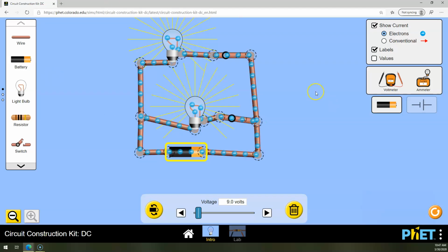This is called a parallel circuit because, well, if it's drawn like this, these two things are parallel, but anytime the coulombs, anytime the current has a choice which way to go, it's called a parallel circuit. Earlier, when I didn't give it a choice, I put the light bulbs all in a row. It's called a series circuit because it has to go to each one of them in series. It has to go to this one, and then this one, and then this one. So this is a good visual demonstration that when I split like this, I don't change the voltage.